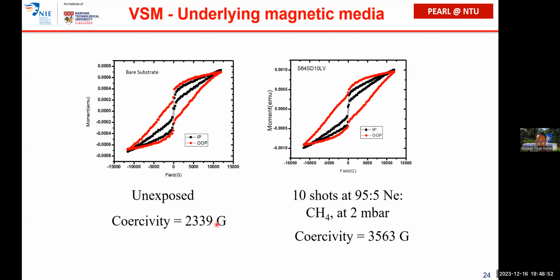The main thing is that these are the materials which are going to store the information in the magnetization. Basically, the coercivity needs to be very high. All these materials which are used for magnetic recording are hard magnetic materials. Hard magnetic is anything above 100 Oersted for the coercivity value, the HC value. But normally they are much more, thousands or even a few thousands.